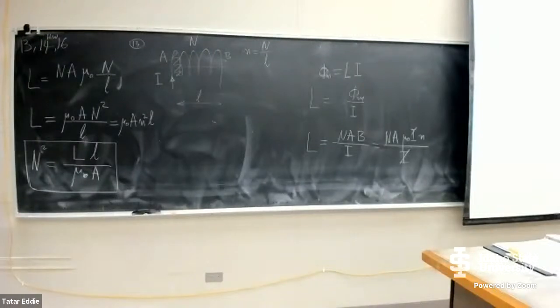This is the standard. A typical setup uses two large coils that are parallel to each other and have a common axis. Because of mutual induction, the AC generator connected to the primary coil causes an EMF that has a certain value in the secondary coil. When someone without a metal object walks through the coil, the mutual inductance and thus the induced EMF doesn't change much, because the magnetic properties of water and our tissues are pretty close to the magnetic properties of air or vacuum.